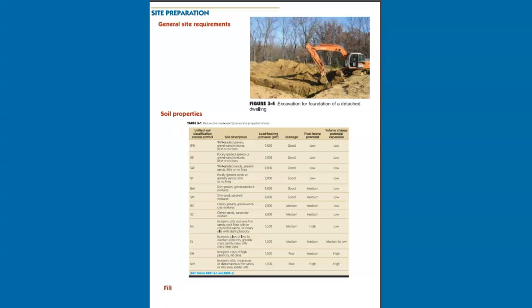If found to be of a poorer grade than the presumed value, testing or mitigation is required prior to placing concrete footings. The builder always has the option of providing the results of soil testing in a geotechnical report in order to use a higher load-bearing value than would otherwise be presumed. Ref. R